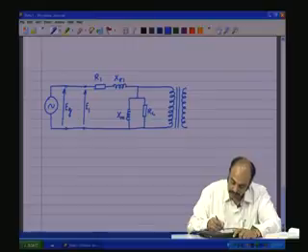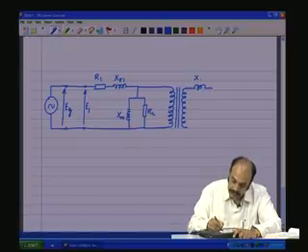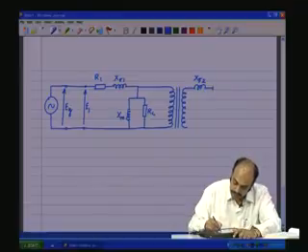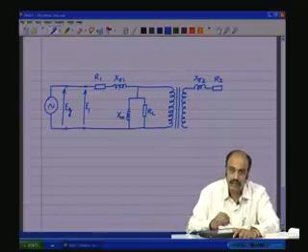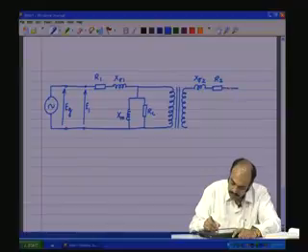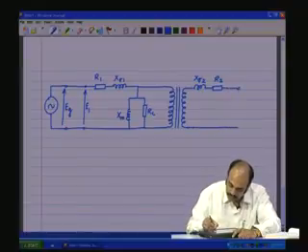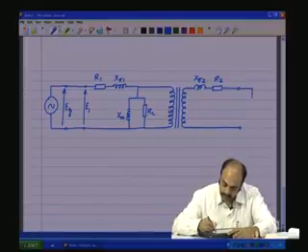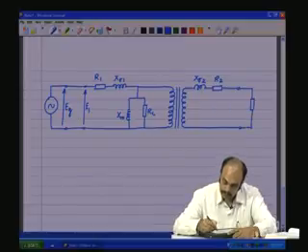The ideal transformer. The secondary of the ideal transformer contains the leakage reactance of the secondary. This is followed by the resistance of the secondary coil, N2 turns, and that gets terminated as the secondary terminals, and there we have the load across the secondary terminals.